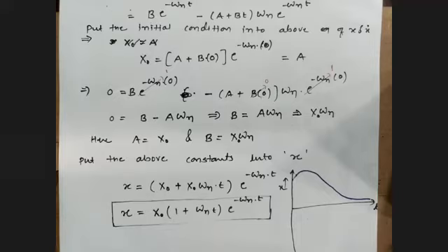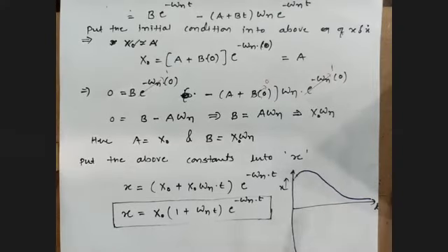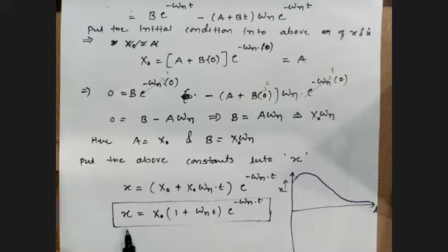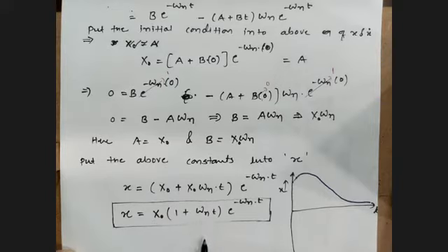Okay, fine. So now, what is the conclusion here? Look at this equation first. This is the response equation, which is in terms of initial displacement and natural frequency. Once you disturb the system initially, the behavior of the system does not directly depend on this displacement, because it is an initial value. You just displace the system by some amount and let it vibrate, right?